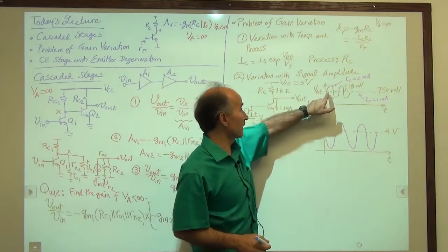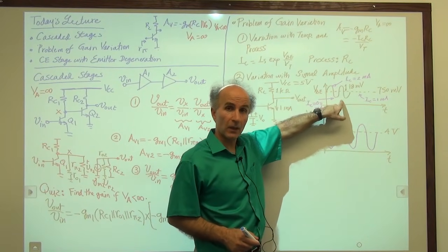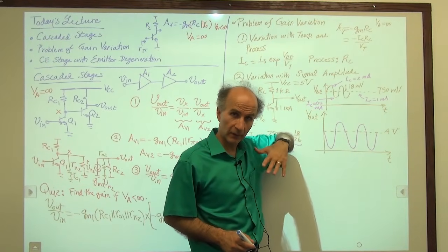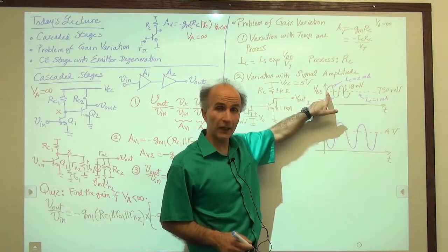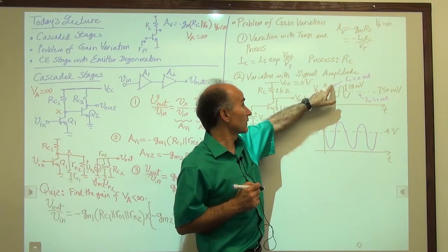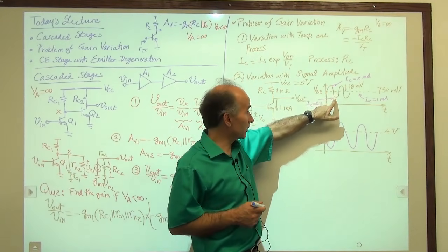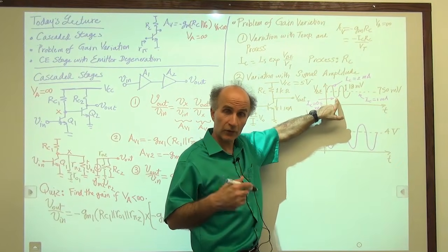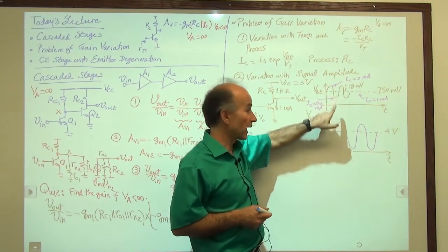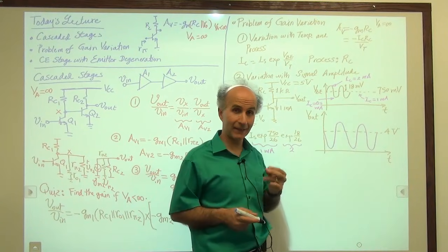The GM has some amount and then it goes up because the collector current is going up so much, and comes down. So the gain of the amplifier changes with the signal level. The gain of the amplifier is minus 38. Remember from our previous calculations? Here. Then it goes up to maybe a factor of 2, minus 76. And then it comes down to minus 38 divided by 2, minus 19. So the gain changes considerably as the base emitter voltage changes by plus minus 18 millivolts.